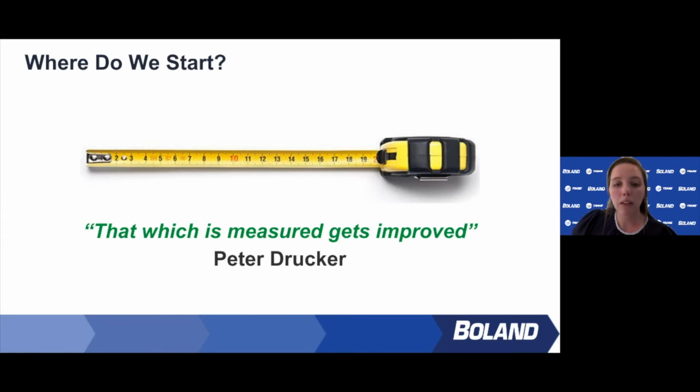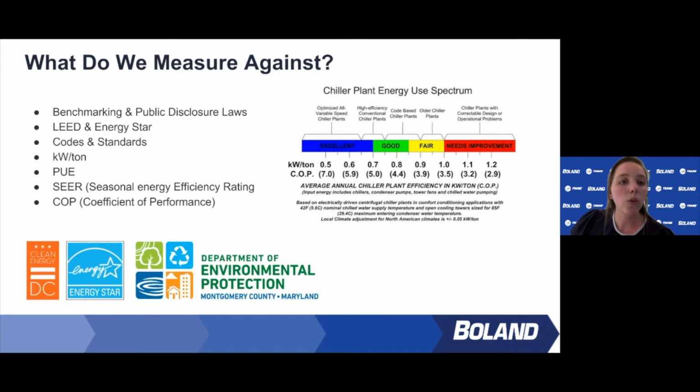First, you need to create a baseline to figure out where you've been, so your historical usage, where you're going, and this could be in comparison to like a personal goal or a corporate goal, for example, like an Energy Star score. So now, what do we measure against? So here's a list of what we use to measure, from overarching legislation codes, which we've seen a lot more of now, to specific equipment performance, chiller plant performance, and also even the efficiency in a data center with your PUE, a power usage effectiveness rating.